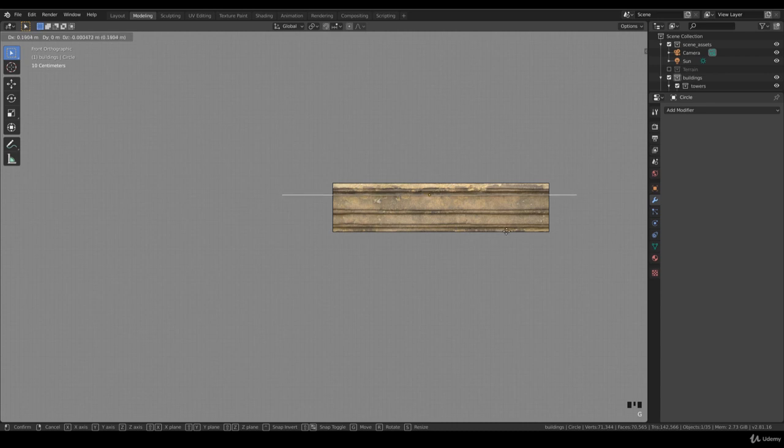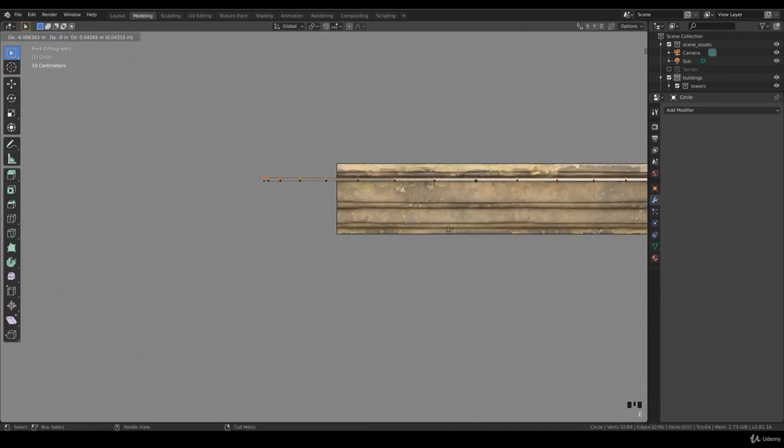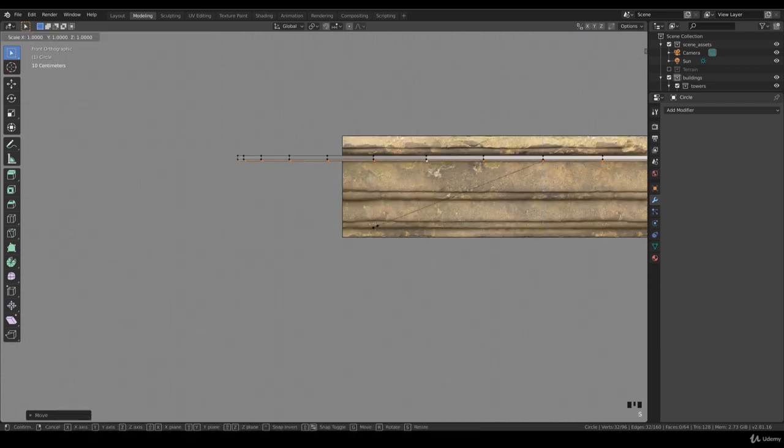This is way better. We got all the space. And we put this right there. And let's start extruding it, so I press E. And I have to find the right way where to start. Alt left mouse click, G Z, and turn it a little bit more upwards, and scale this down to the bottom, and scale it, just very gentle. And Alt left mouse click, and we continue doing this, and we scale it, and we scale this even more, and put this down, and right there, and one more time, and put this right inside.